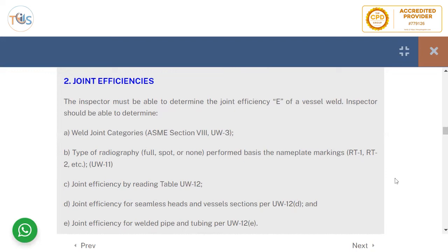The longitudinal weld sees almost twice the stress of the circumferential weld because of the hoop stress. You can also see from the formula calculating the thickness for a certain pressure that the thickness would be twice for the longitudinal weld because it experiences twice the load under the same pressure. So that would be the deciding factor.